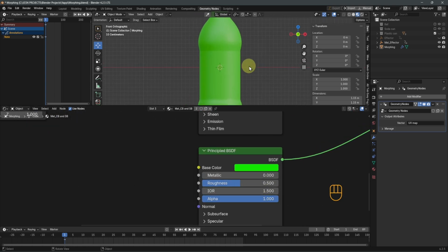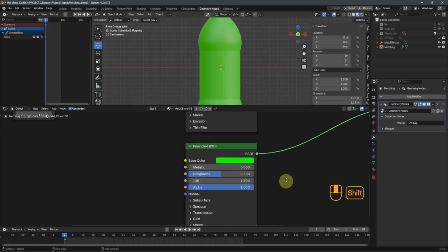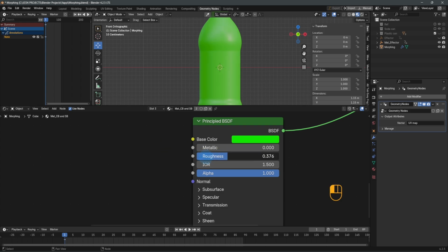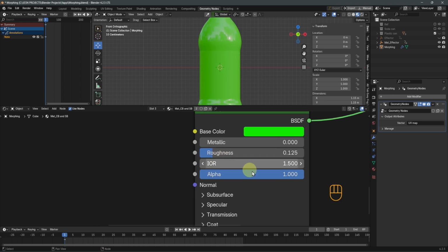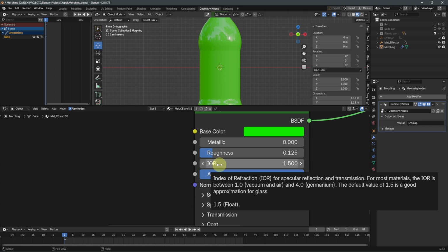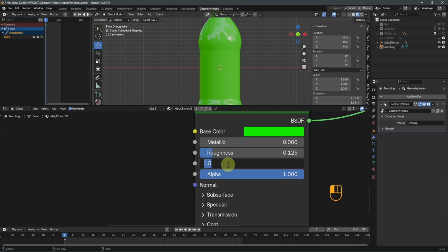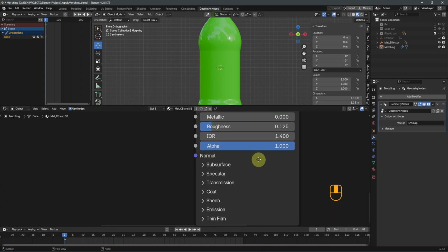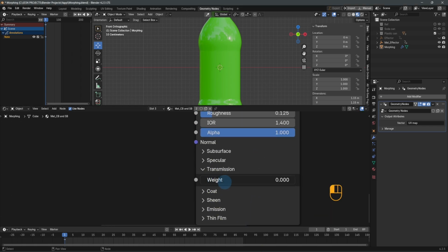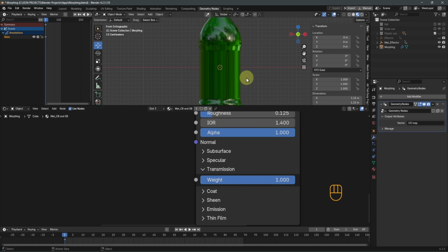So you know that the body around here is what has the name of the plastic can, but this time around I'm not going to give it any name because this video is going to take forever. So I'm going to reduce the roughness. The index of refraction for a can is about 1.4. Okay, so 1.3 to 1.7. So let's just use 1.4, and then I'm going to give transmission weight to be 1.